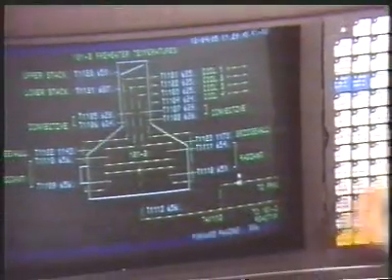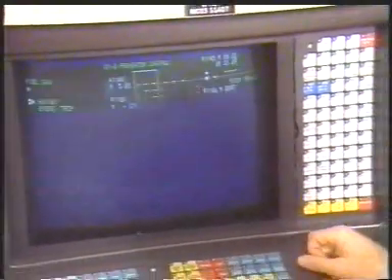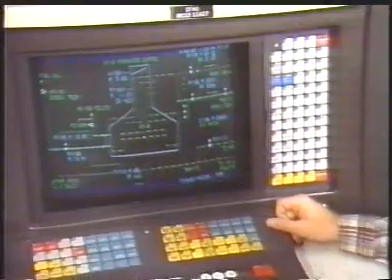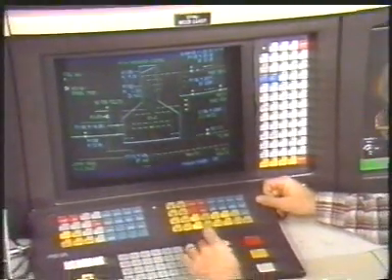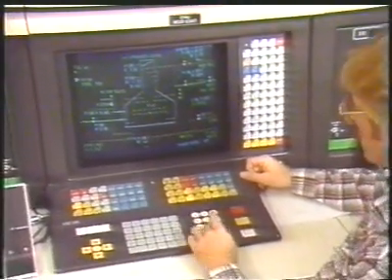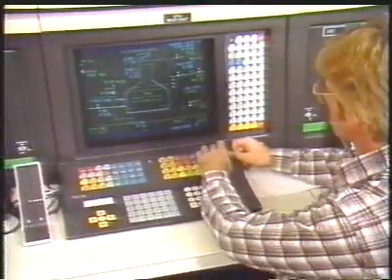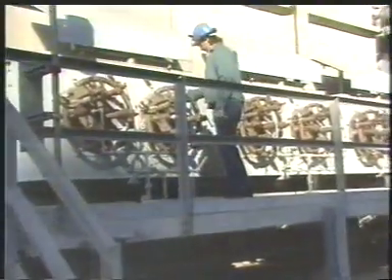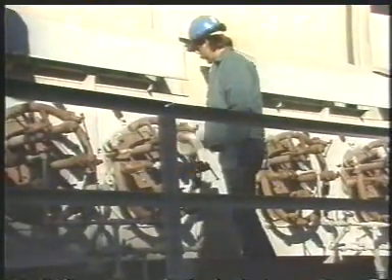Sometimes hot spots on the furnace tubes can be corrected by redistributing the process flow so that the hotter pass of tubes receives more charge. The increased flow of charge absorbs more heat and carries it away from the hot tubes. In other situations, it may be necessary to reposition a burner or remove it from service.